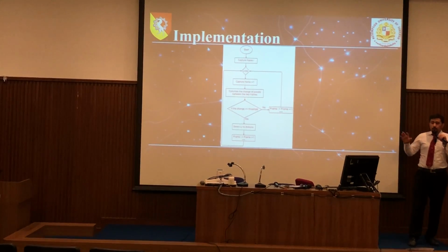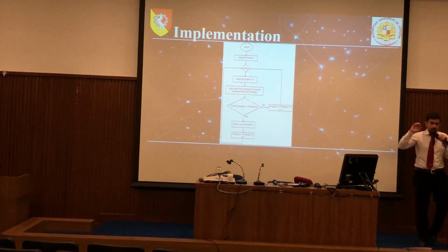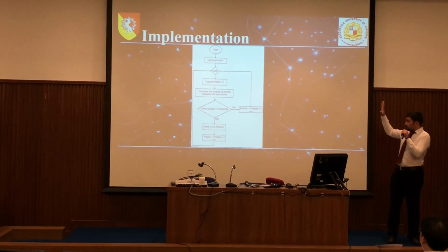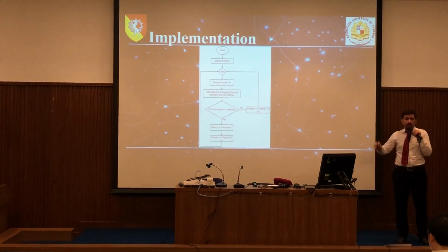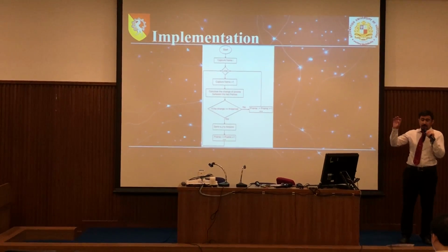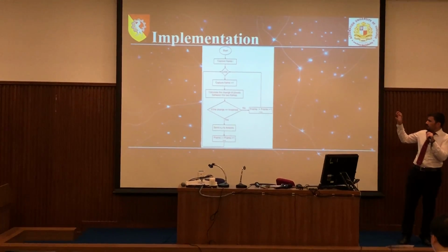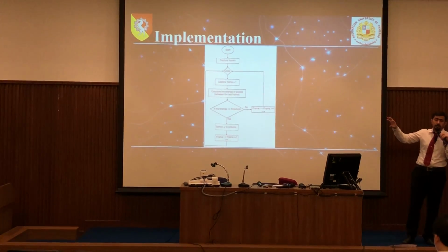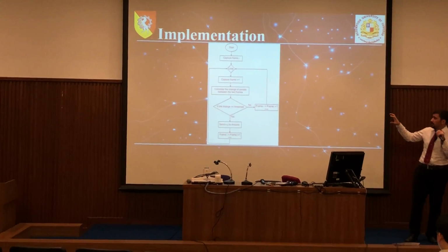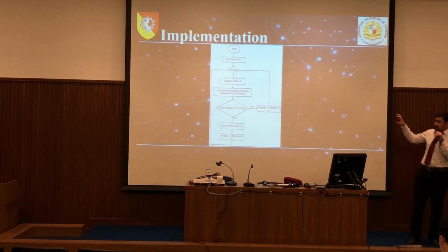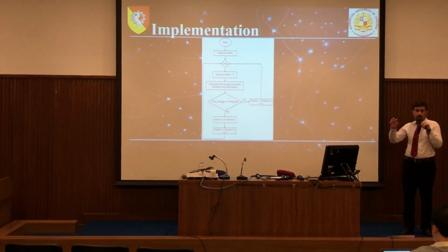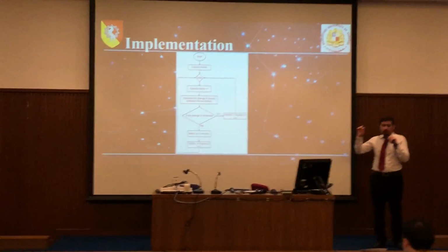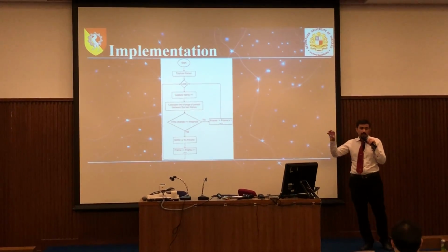The software part works as follows. First, it will capture a frame from the camera, and shortly after that it will capture another one, and respectively compare each pixel from the first frame with the same pixel position of the second one. And when there are changes, it returns the XY coordinate of that pixel.